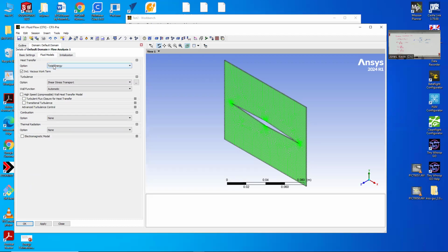So this was the heat equation, or energy equation, they call it. It's a huge equation actually. It's quite a painful one to solve. But it brings in a relationship between all the velocities, density, pressure, and temperature. So now since we've thrown temperature in the mix, we now have 6 unknowns and only 5 equations.